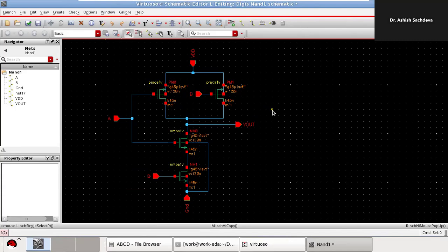of a circuit, never ever take two signals with the same name. If it is the case in your circuit, please short them and keep them one name, right? So what I'll do, I'll delete one of them.